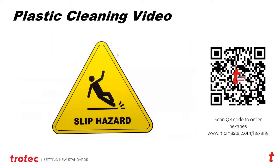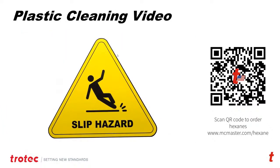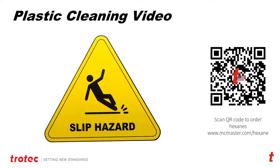And this is a good laser hack that you can kind of see. It kind of brings that detail out. If you get a little bit of haze or residue that does form from your engraving process, the hexanes are a great tip. So using your air assist, using your cutting grid, engraving it with the right settings, engraving from the bottom up into the color contrast you want, and then using a little hexane cleaner to clean the material out so that you can get that nice finished, polished looking laser engraved plastic sign.